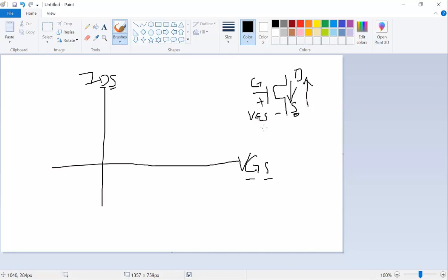So now we are engineers, electrical engineers, learning how to operate this transistor. Keep in mind, we just bought this transistor and put it in the lab, and we'll learn how to use it. That's what we are doing now. The transistor you can turn on and turn off, just 2 states for digital. In analog, they have millions of states, different voltages, but in digital, it's just on and off. Now the input voltage could be 0 or 5 volts. Digital is just 1, 0. 1 is logic 1, which is 5 volts in this case. So 5 volts is being provided here.